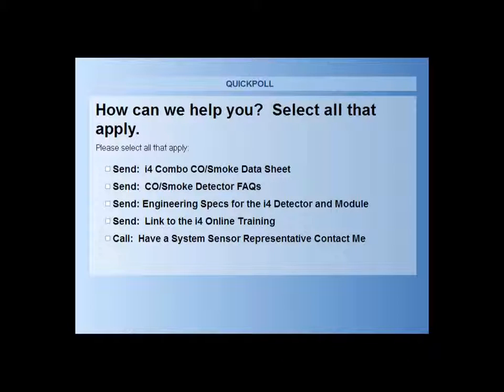Justin, I know Jackie offered this as an offline answer too, but it's been asked again. When CO comes from a fuel source, it's warmer than the air. So wouldn't CO from wood burning or burning fuel be warmer than air and tend to rise initially? Yeah, if the air itself is warm, it is naturally going to rise. That all depends on the appliance that is releasing the carbon monoxide into the air. However, we want to clarify that once it is in the air, even if it starts off warm and rises, it does quickly disperse into a well-mixed state within that environment.